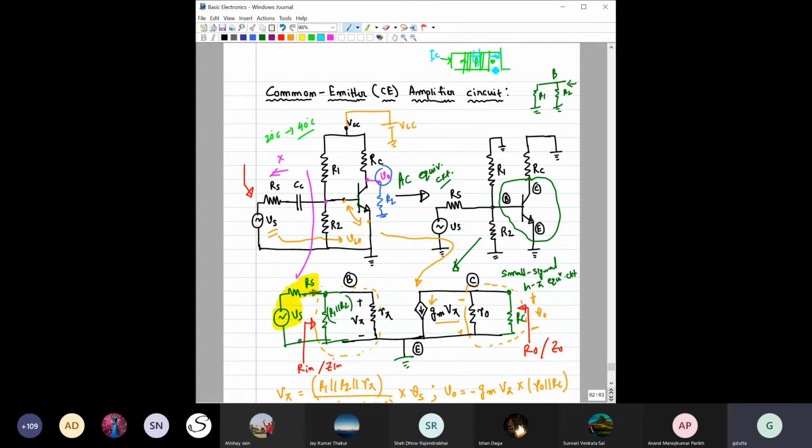The more the drop across this transistor, the more the power dissipation, which means the temperature will further rise. So once again the temperature will rise. Now as the temperature rises again, the junction temperature increases, that increases IB, that increases IC, and again that IC will increase the temperature. So once the temperature increases, the circuit will try to fall into a positive feedback loop.